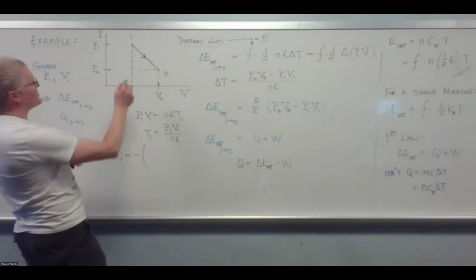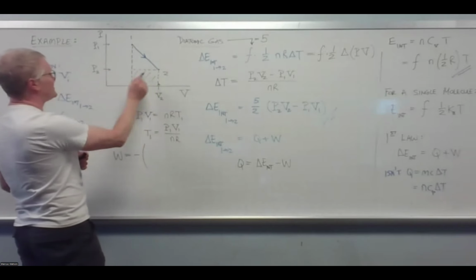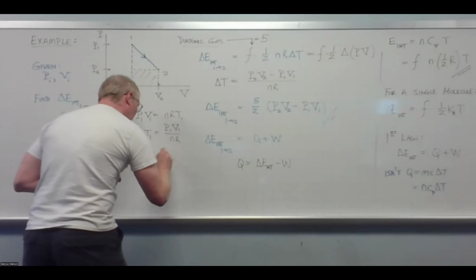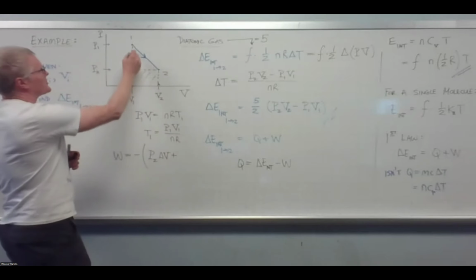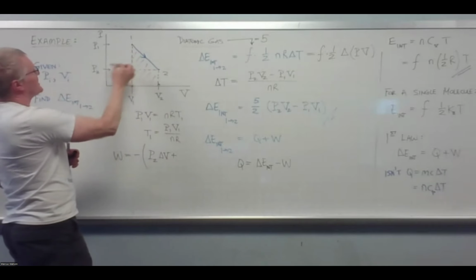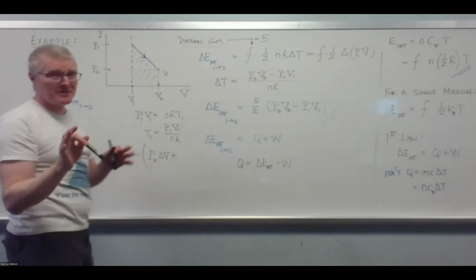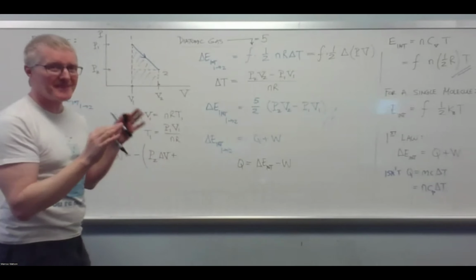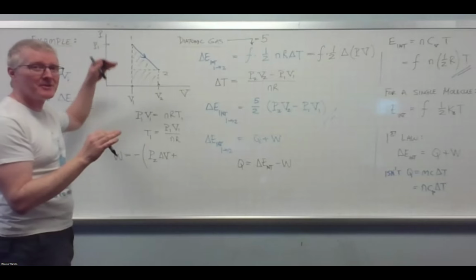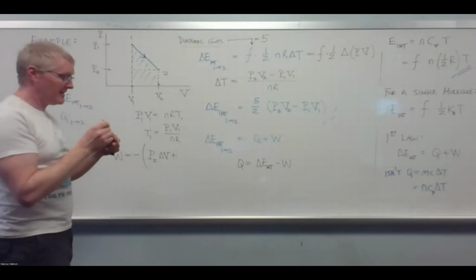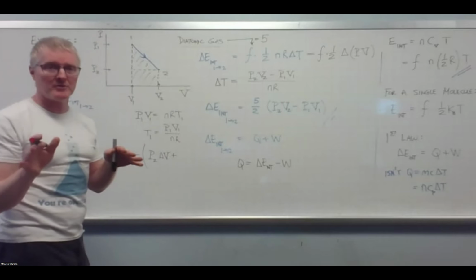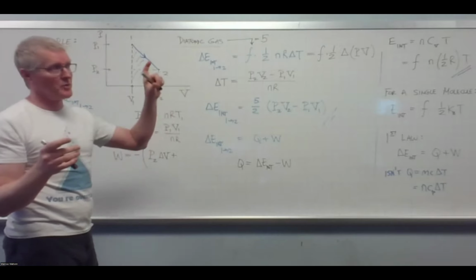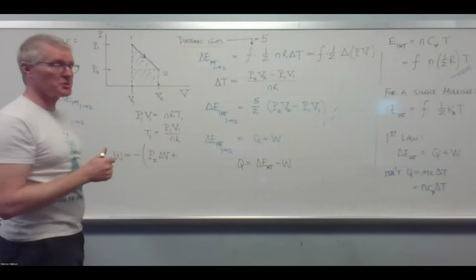And that means I'm going to do the first piece here, which is P2 times delta V. That's isobaric, that's no problem. And I'm going to add to that the triangle up here, which is, well, now you'd want to be careful because it's tempting to go P2 minus P1, but that's not going to give you a positive number. You need a positive area here. And if you've had 4A with me, you know what I'm talking about. When it's like a VT of a velocity time graph, you want to do the positive leg of the velocity triangle.